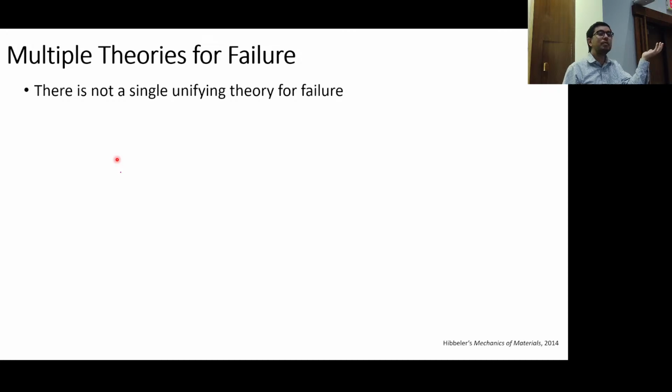Why would that be? Well, finite element means that the elements all have a particular size. And a crack is a very, very small fissure in the material. So it's very hard to discretize a material or a structure sufficiently to get the correct idea of fracture.